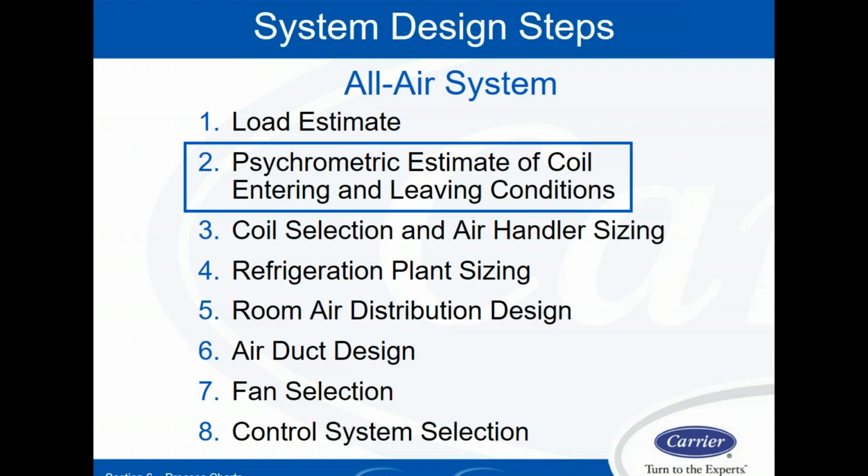My duct design is based off the load calcs of the room, smaller ducts to rooms that need less cooling, bigger ducts to the other rooms, obviously. Then once my duct is designed, then I can pick my fan system. Then I can decide how I'm going to control the whole dang thing. So this is just one of many pieces of the design process.